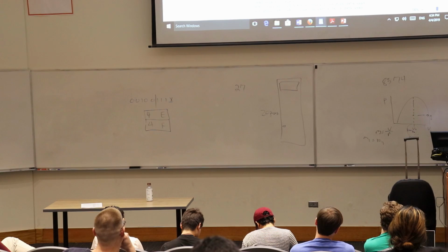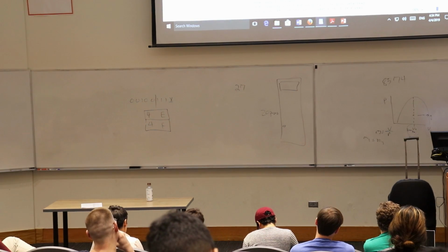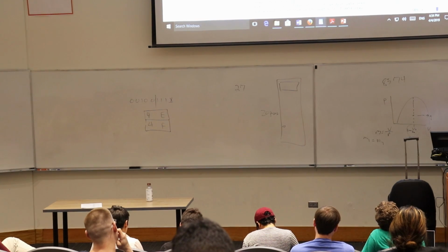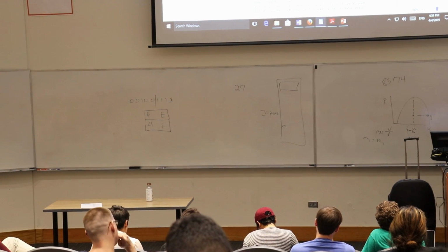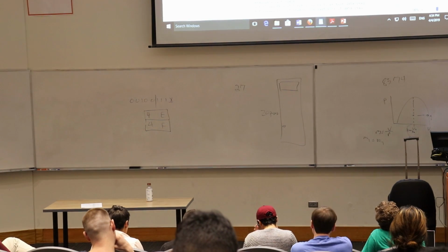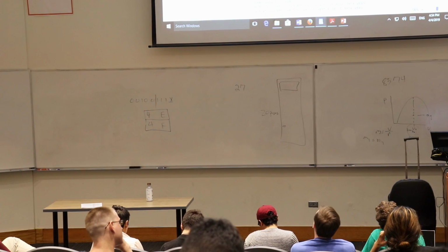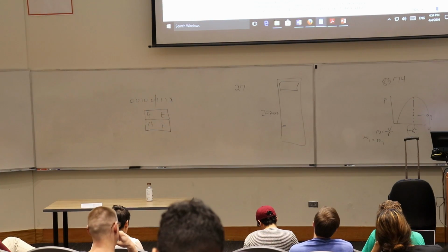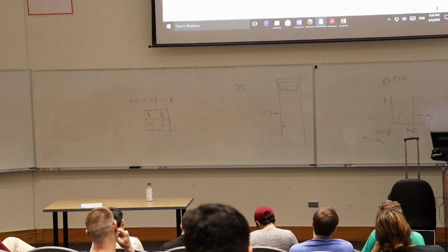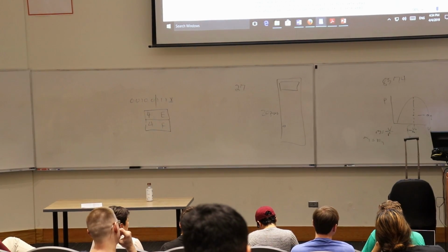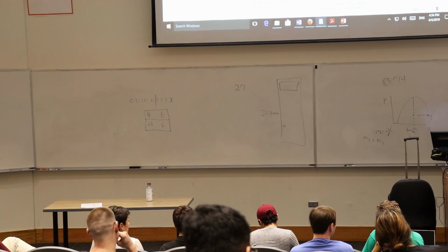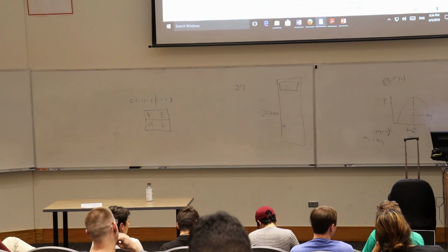And most of these devices have all these extra registers. They just drive you insane. But usually they make it so that if you just use the default start point, they work pretty well for most purposes. But for instance, let's say you're using an accelerometer to stabilize the image. So how many of you have cameras that are motion stabilized? Yeah, they use an accelerometer. That's how they do it. And the shutter, when you punch the button, doesn't really take the picture.